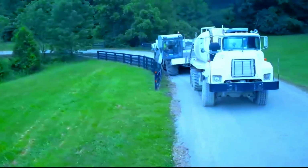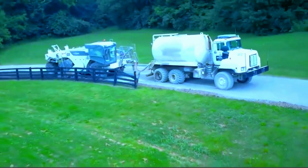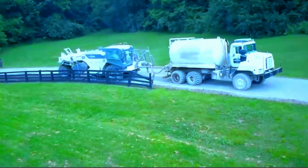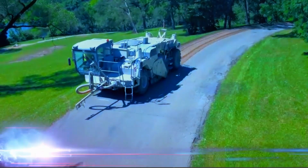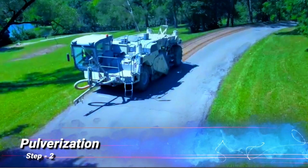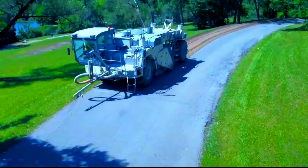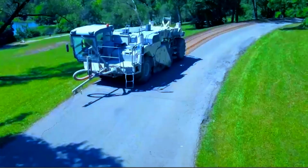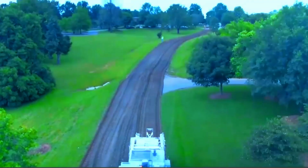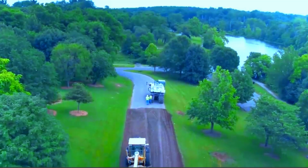Based on the material properties, a suitable stabilizing agent is selected. This could be cement, lime, asphalt emulsion, or other additives. Step 2. Pulverization of existing pavement. A specialized machine called a reclaimer is used to mill and pulverize the existing asphalt and base layers to the required depth. The pulverized material is left in place, ready for stabilization.